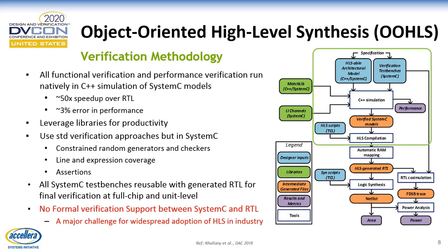In order to verify the design, we have our test benches also in SystemC. A key difference here is that we perform both the functional and performance verification natively using C++ simulations. There are a few major advantages to this approach. First, as mentioned before, we achieve about 50x speedup while doing C++ and SystemC simulations over RTL. As a result, we have faster debug cycles and quick turnaround times.